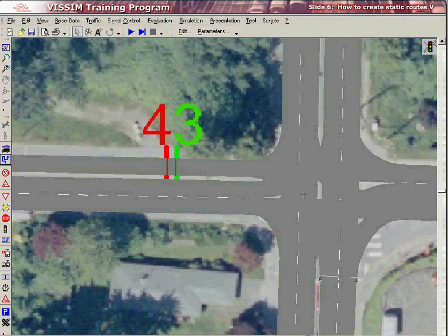If you had accidentally placed the end of one of your routes after the start of the next, the vehicle would not be able to get on the route and would randomly select turns, taking the first connector approached in its current lane until it crossed another routing decision or left the network. If you have accidentally done this, you will need to move the end of the route.